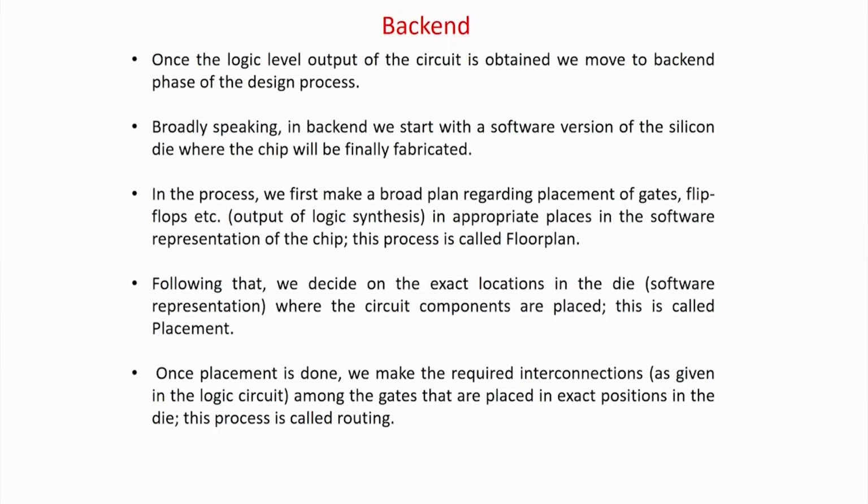Then once the gate level is done, basically you have to fabricate the circuit in terms of layout. So there will be a die, so you will have some rows and columns. So the gates have to be placed, and that is actually called the floor plan. Wherever which gates will be put, where will be the memory blocks. So broad level placement we do about the gates, which is called the floor plan, and then finally all the gates will be placed, which is called the placement, and finally based on the requirements of the circuit they have to be properly connected, which is called routing.